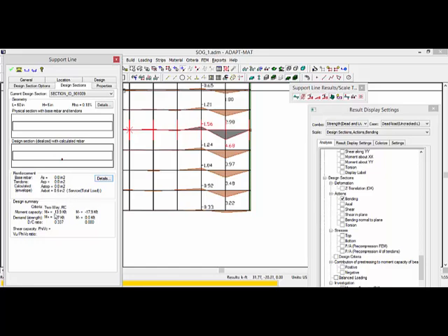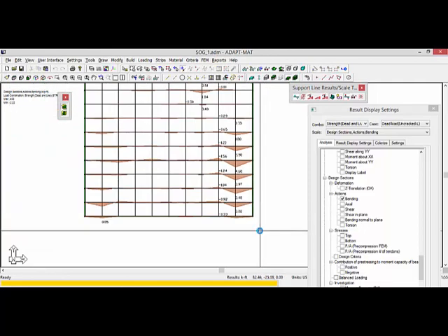The program has enough capacity based on just the fiber to meet the strength demand, but we are adding a little bit of rebar again for the purpose of serviceability. If we ran the slab without the surface reinforcement or the surface combinations, we would have no additional rebar needed for this case. And we'll go ahead and close that.